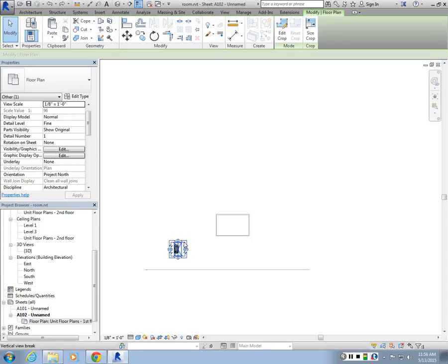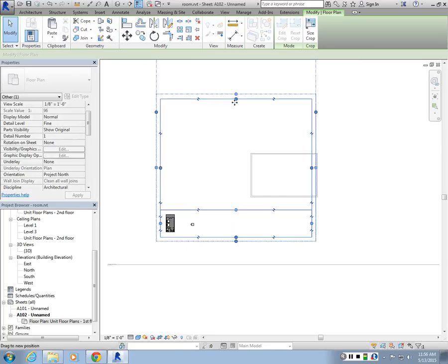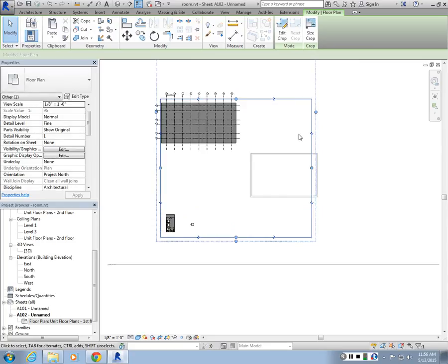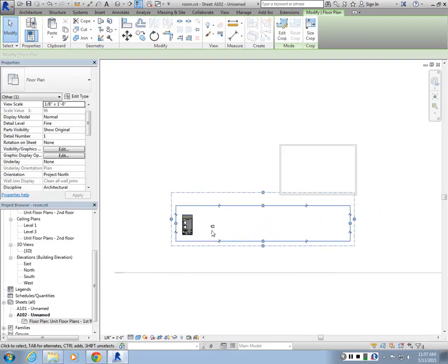That's the part you want to draft. So you're referring to the floor plan, but you're filtering out stuff that you don't want to see. This is basically what those regions do. If I extend these, I would include more information that may be in that file. Your floor units may be drawn side by side, so you may want to keep all of them together.